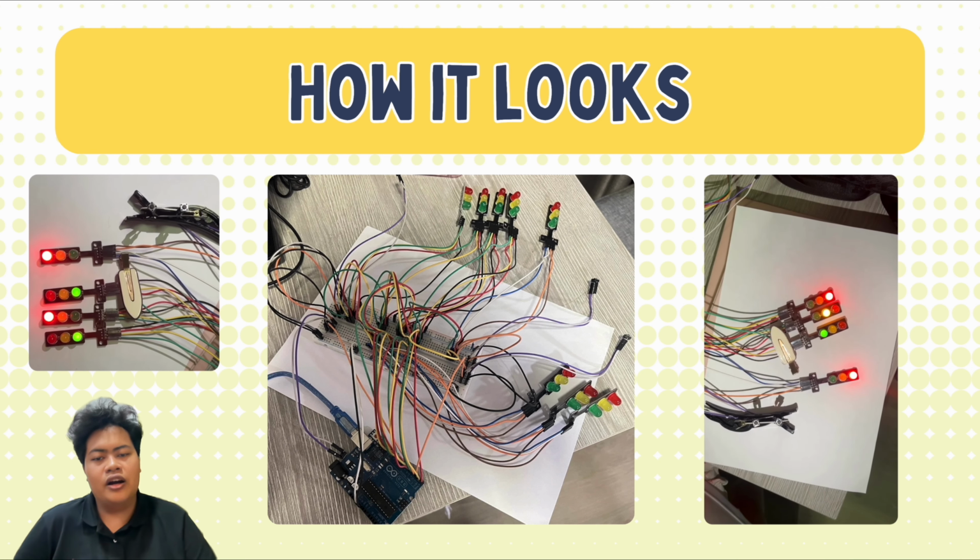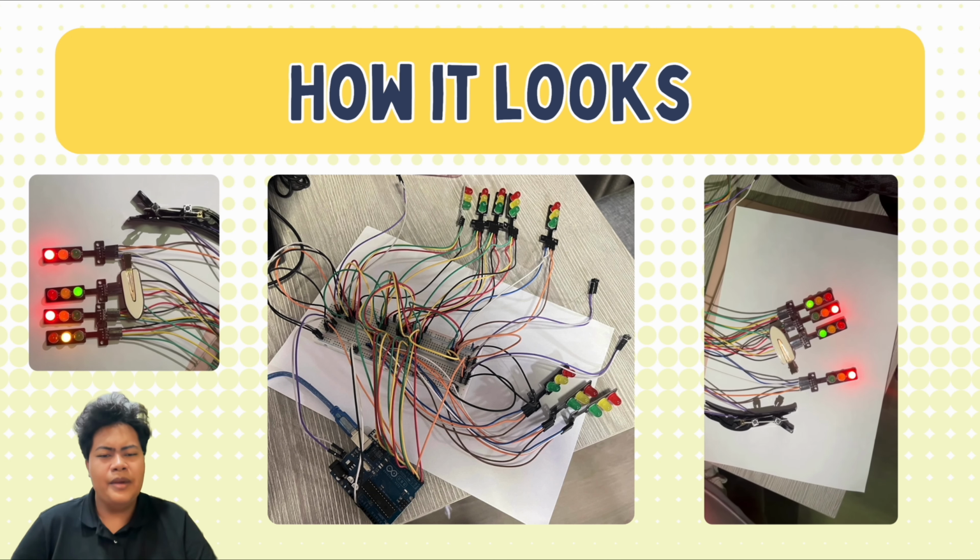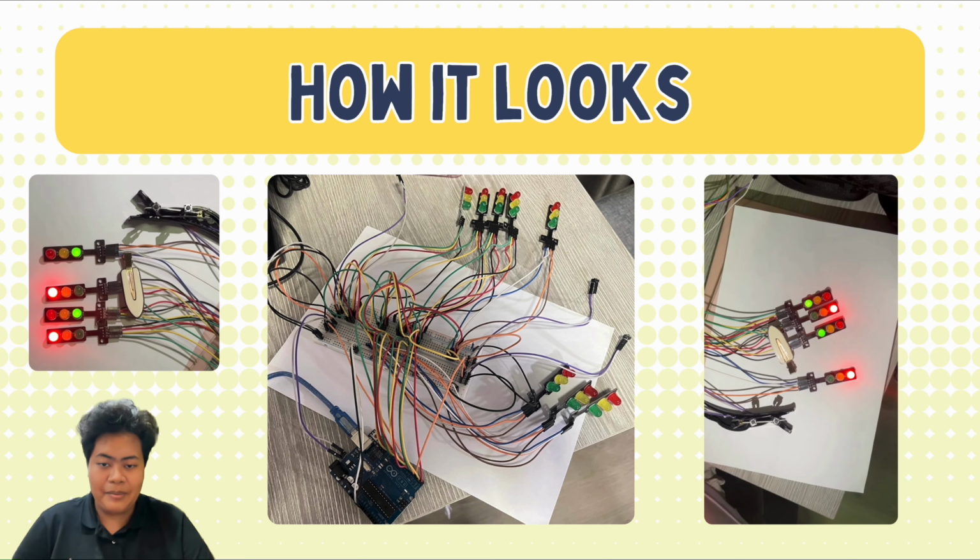The left turn signals are wired separately and are linked to the pedestrian light using reverse red and green wire. This means when cars cannot turn left, pedestrians are allowed to cross, making sure the two actions never happen at the same time.